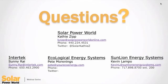Does that make sense? It does. So yes, we're still talking in a string scenario. However, the panels are not strung together. The optimizers are strung together. In a smart module, that's kind of confusing. When you're talking about a separate add-on piece, the panel is mounted to the optimizer in parallel, and then the optimizers are then strung together.